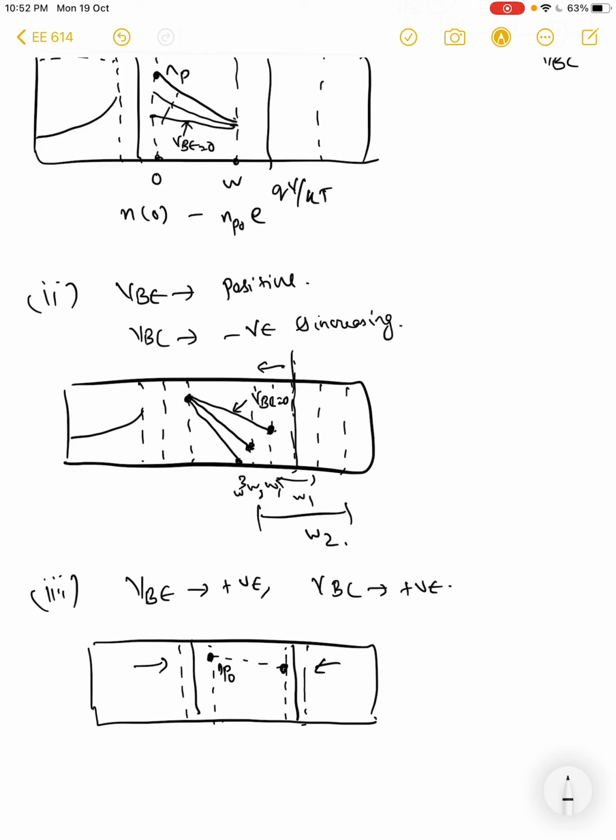And if there is no big gradient, right? So as you increase the collector bias, as you increase the forward bias in the collector base junction, you are increasing the injection into the base, so that you will very quickly remove the carrier concentration difference in the base, leading to very low diffusion currents, right? Now as you reduce the forward concentration, the carrier concentration in the base can reduce. This will lead to higher currents.